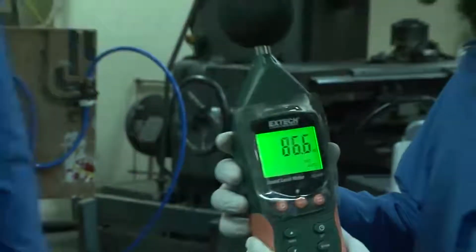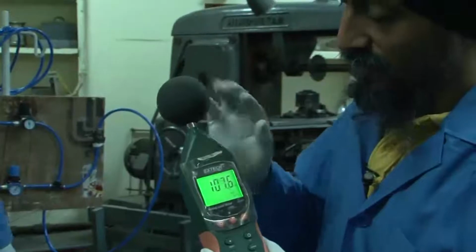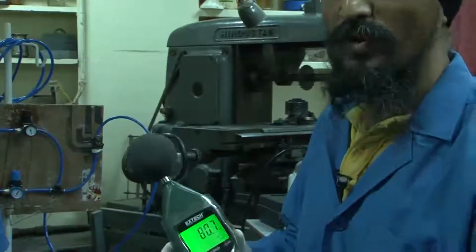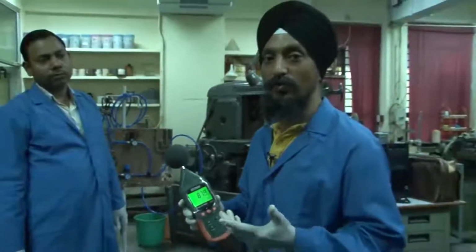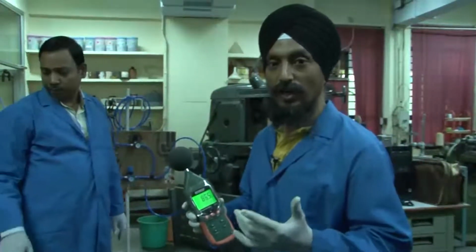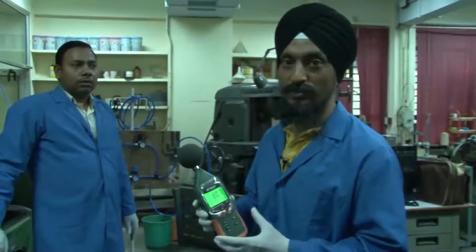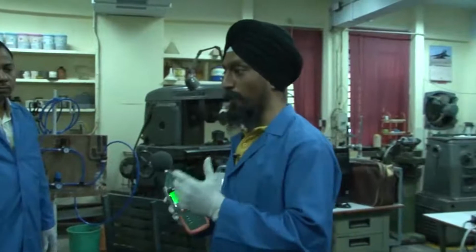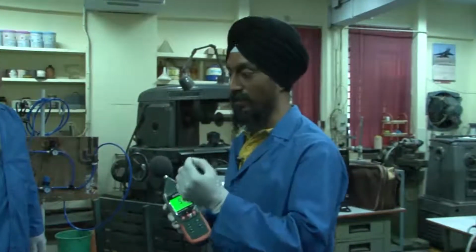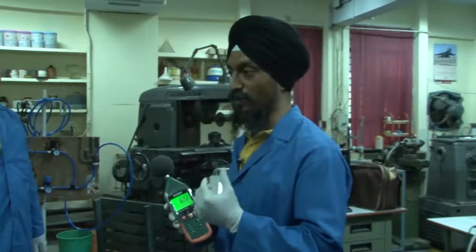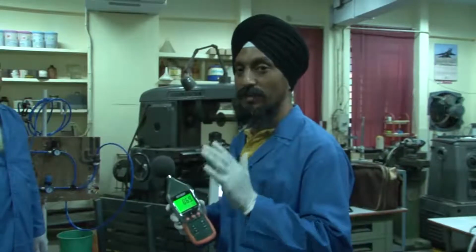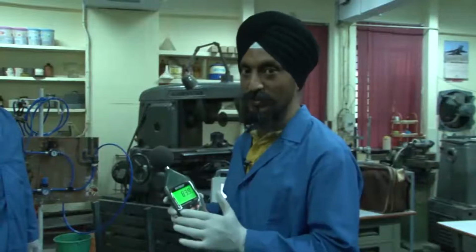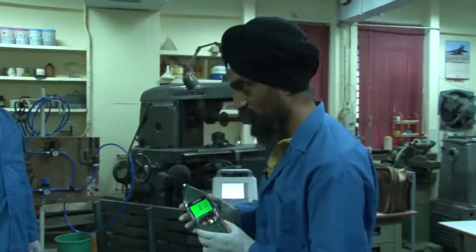You can see the sound raised to even 107 decibels here. And in an office kind of environment, as I already mentioned, 55 decibels is the acceptable sound level. This will record that. The peak sound events we receive here should be fewer than 10 per day, which is the recommended limit in the industry, specifically in India. This is another instrument able to record sound.